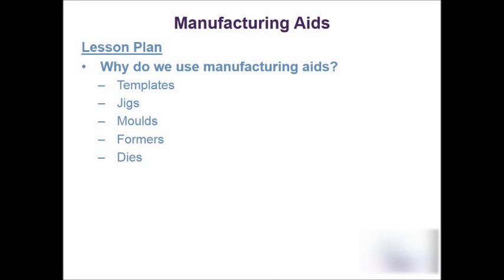So if we talk about extrusion, the best way to think about this is perhaps think about a toothpaste container. Now if my toothpaste container is filled up with toothpaste and I squeeze one end, I apply pressure to the toothpaste, it forces it out of the die, which is basically the nozzle. So in a normal toothpaste tube, the nozzle is circular, and therefore I will get a circular extrusion coming through this circular die. If I change the shape of the nozzle of my toothpaste to a triangle, I would get a triangular extrusion. If I change it to a star, I would get a star-shaped extrusion, and so on and so forth.